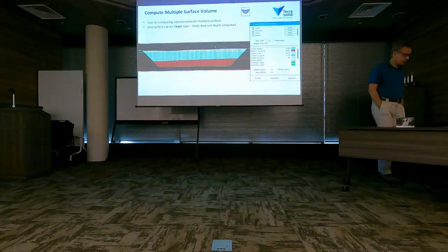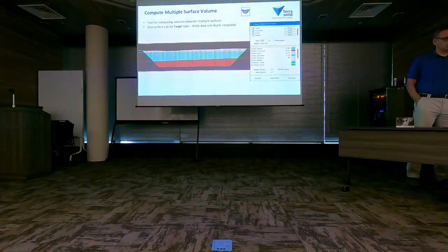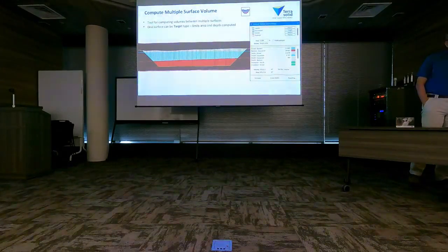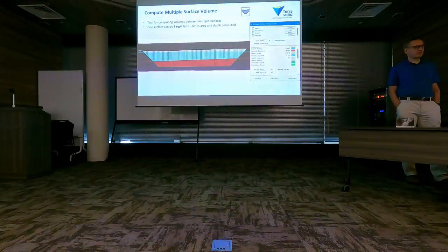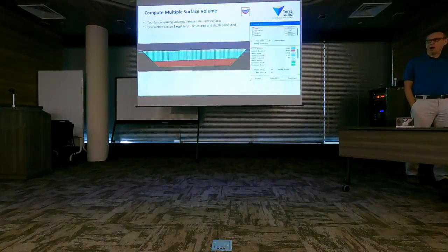Then there's another new tool which is called Compute Multiple Surface Volume. And this one I would use if I have many TIN models. As the next new feature, it calculates volumes using multiple TIN models. And typically, I would have the ground surface.